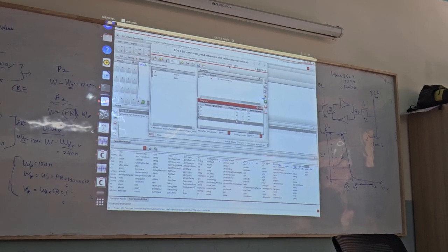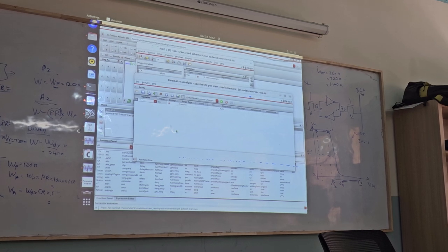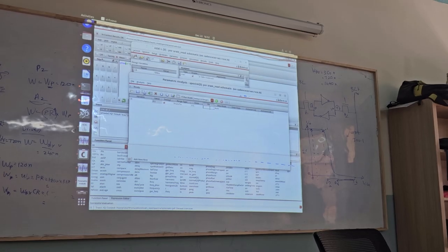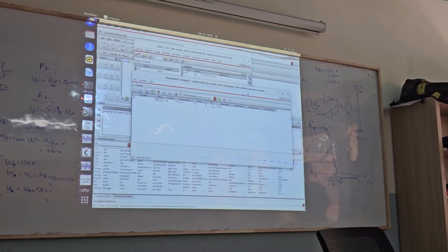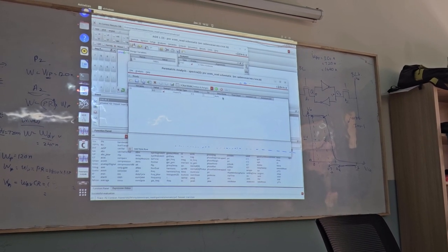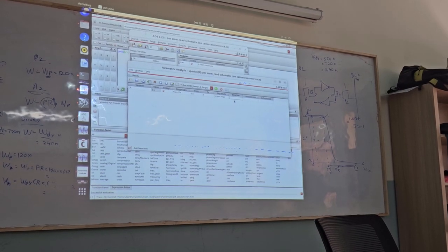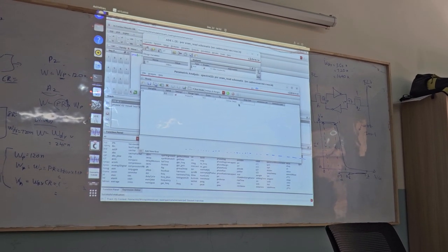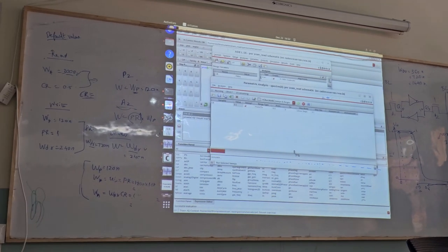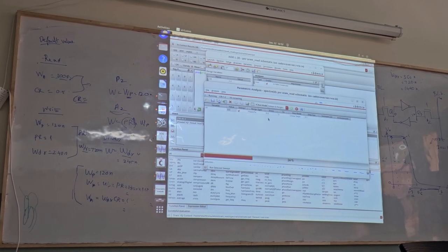Okay, now go to Tools, Parametric, and under this variable select CR and change this one from 0.6, and I will just have a maximum value of 3, okay, because I know the value that we will end up having, so I will not run it till 5 as it is given in the manual. Okay? I will just stop it at 3, and here I am just giving a step size of 0.1, and when I run it, we are trying to increase the value of this NMOS transistor, the pull down transistor.